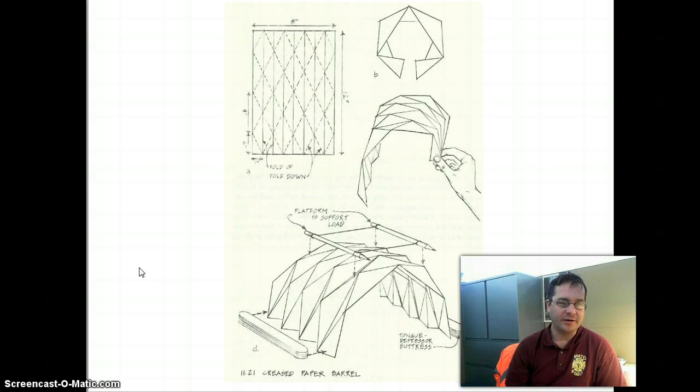This is a slightly more complex folded sheet arrangement, but the principle is the same, that you're separating the extreme fibers of the material to create this kind of complex and rigid shape. This would be analogous to perhaps some of the complex curves that are formed in the body of a unibody car. It gets its strength from its geometry.